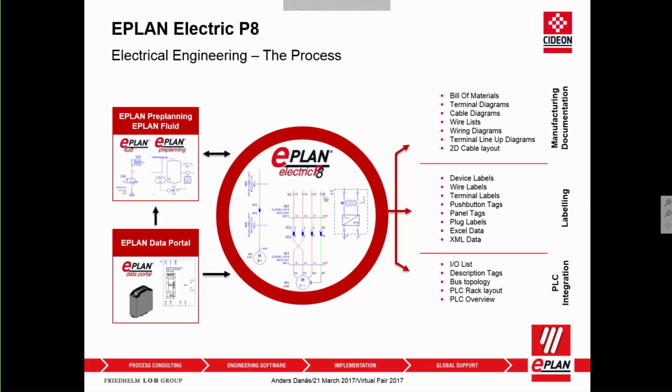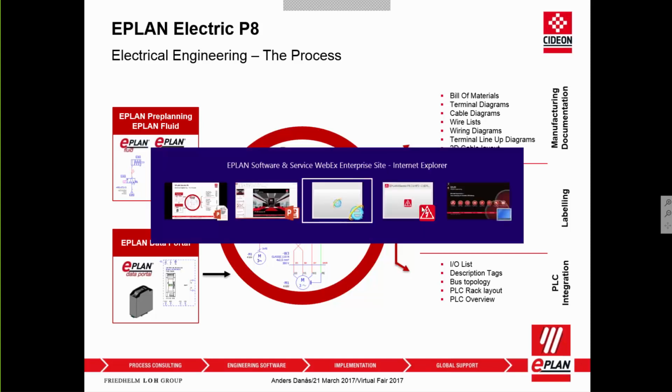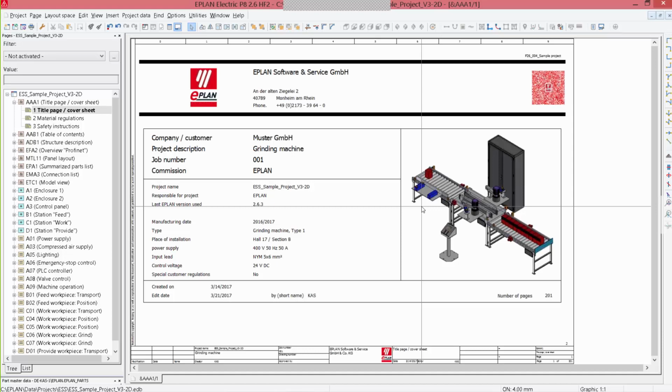Of course, today we don't have time to go through all the different capabilities of our Electric P8 environment. So I'm going to focus my short presentation today on the flexible design method. This is, I believe, a very important aspect of the Electric P8 environment, to be able to start at any time in the project in, for example, single line, or in the 2D panel, or in the multi-line, and all is data consistent between the different environments. When we talk about the flexible engineering method, let me go into the software and give you a live demo to give you some further information.